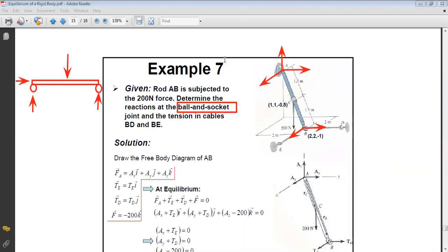We will see how. Now, what are the other forces acting on my bar? I have the weight of my bar, which is equal to 200 Newton. So now I will put my forces. I will annotate them. I have AX, AY, and AZ. Okay. So now, the step is like in particles. Same, we follow a certain methodology. The first equation we write is that the sum of forces as vectors is equal to 0. Of course, the 0 vector.